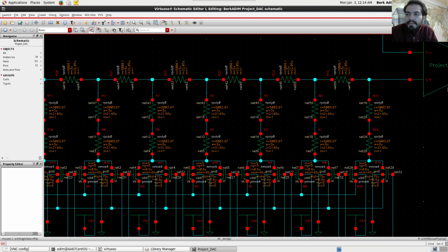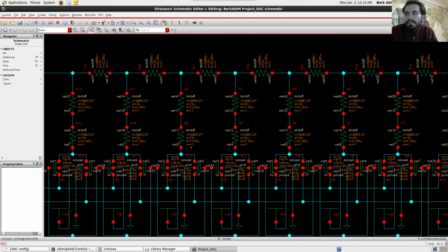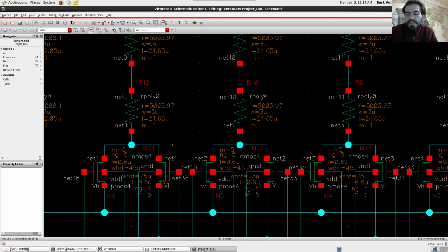So I didn't go for a wider PMOS and narrower NMOS arrangement. I went for quite the opposite, to equalize the capacitances so that we don't get current peaks. And after all, we are not using the process minimum widths here, so the resistances we get from the PMOS and NMOSs are not that huge.